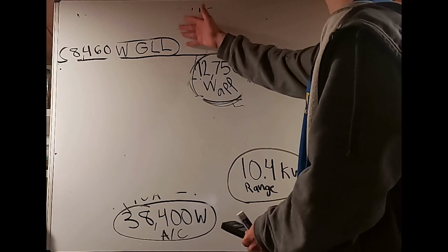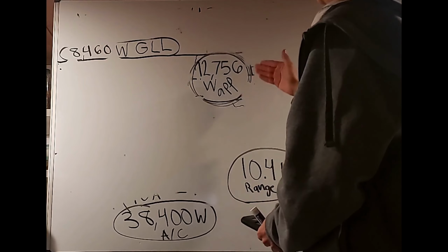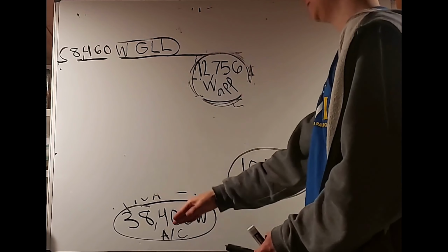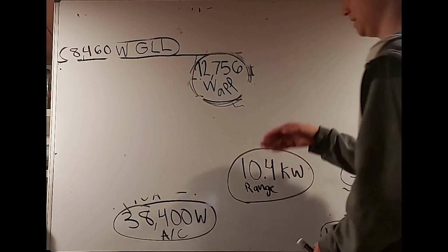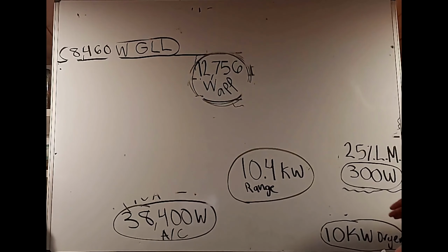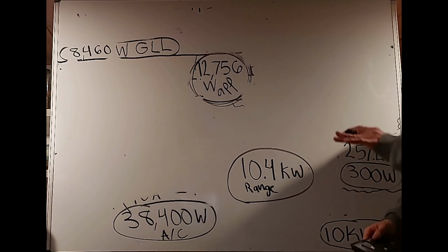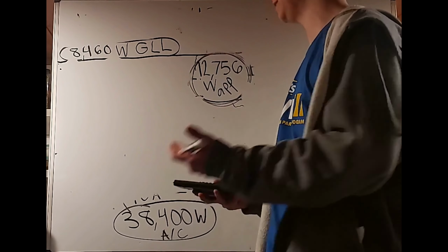You see the general lighting load section has its number. The appliances have its number. We have to pick the bigger of the heater, AC. We see AC with a number. We see the range and the dryer each have a number, and then the 25% of the largest motor also has its number. Now, if you've done this enough times, you know that's everything you got to do. Now we can add everything together.